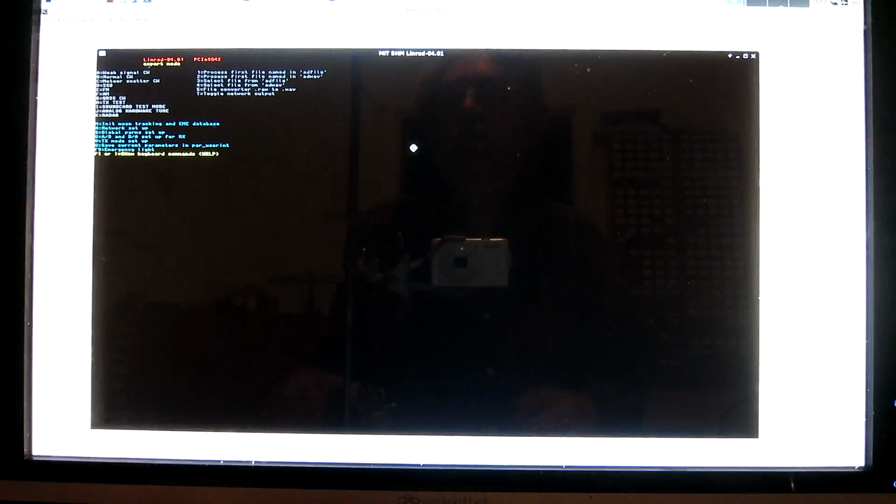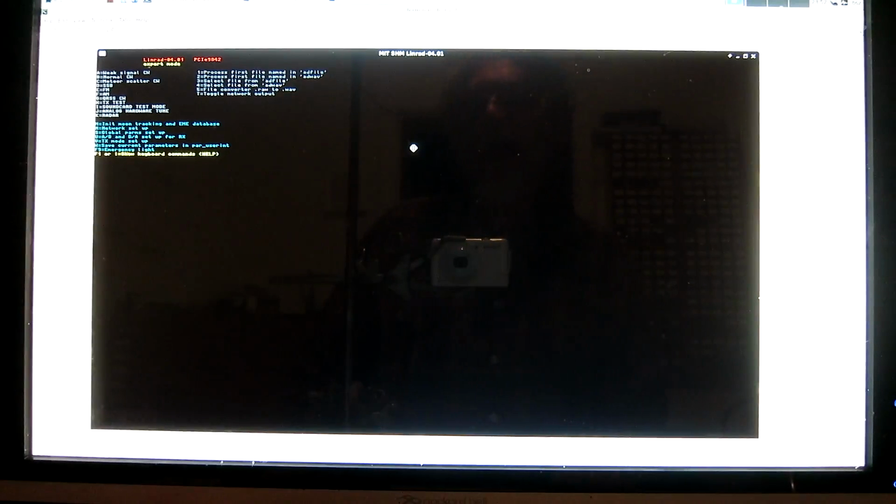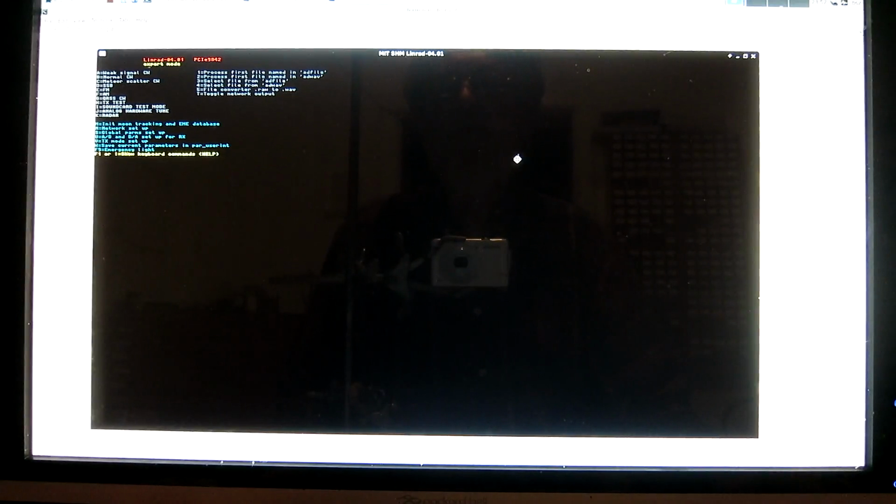This video will show how to measure dynamic range in Linrad, and also a little bit about how to select windows for the FFTs to get a good suppression of aliasing spurs. And I will try to explain how these things work.